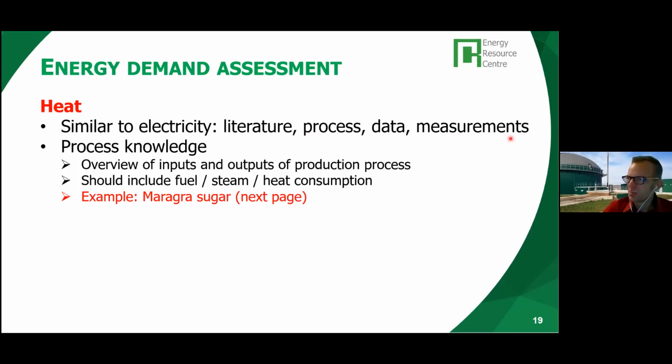And then there are measurements that you might be able to do, although for heat it's a bit more difficult than for electricity in general. As indicated, make sure that you understand the production processes that are taking place. Get your overview of the inputs and outputs. Make sure to include the fuel consumption, the steam consumption, and/or the heat consumption of the different process steps.